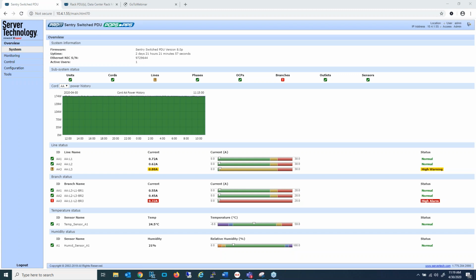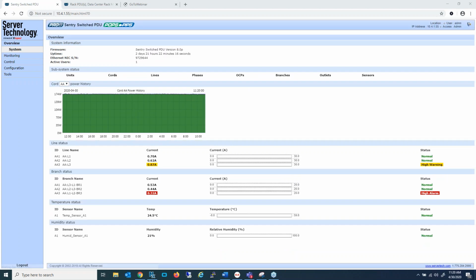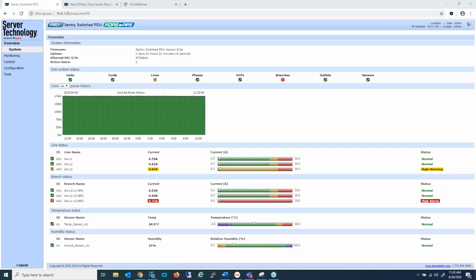It does occur. It's sometimes misunderstood. Typically it's going to be when it's a repeating install of just the same equipment top to the bottom of the cabinet, whether that be 36 or 42 pizza box servers, if people use that term anymore. But yeah, 42 one-use servers or less, the tendency would be to just plug them in top to bottom, and it needs to be done differently. You need to pay attention to balancing between the branches as well as the lines.